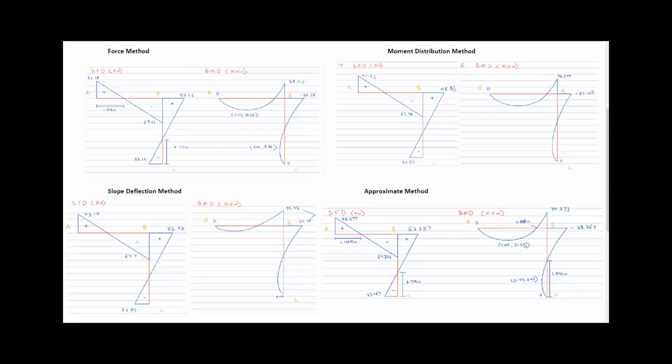In summary, each of the four methods used to analyze indeterminate structures all provide similar results. Variability is introduced in the moment distribution method as I is not held constant anymore, leading to a slight variation in the results of the moment about joint B. In saying that, the shear force diagrams are nearly identical in each method,